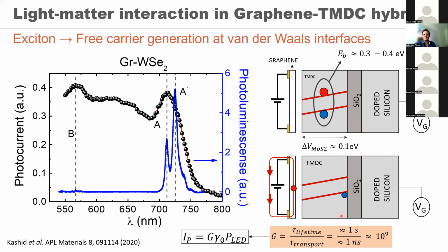Electrons, this is something which is also very inaccurate. Actually, if you have the electric field, it can go to hundreds of seconds without electrons coming back in here. So that's the lifetime of the electron hole pair. Remember, and this tau transport is the transit time of electrons along the graphene layer. It goes between here to here. And given the kind of mobility that you have in these systems, the transit time can be about a nanosecond or a little less than a nanosecond. Okay, sir. Good. Thank you.